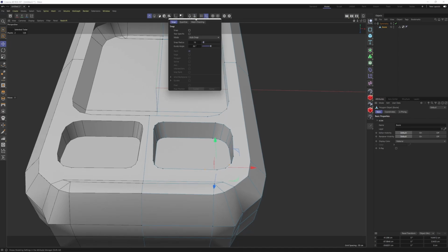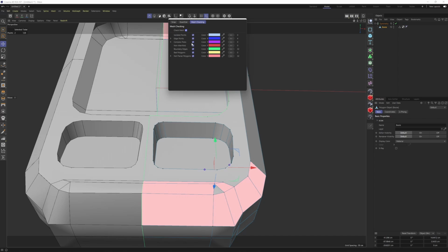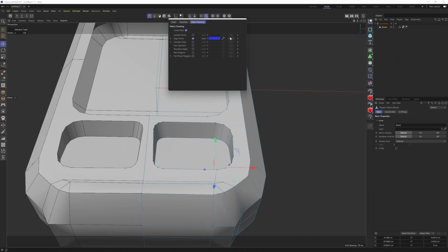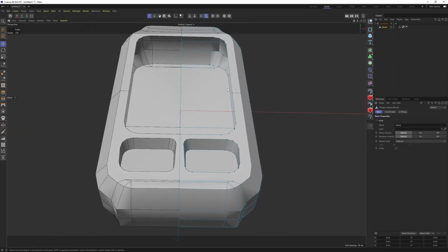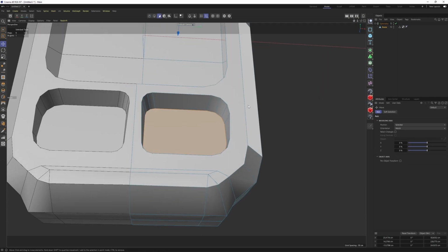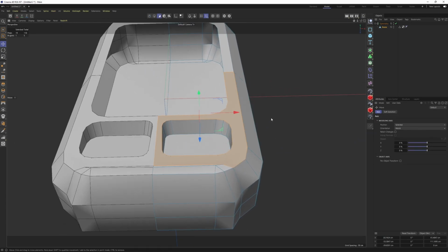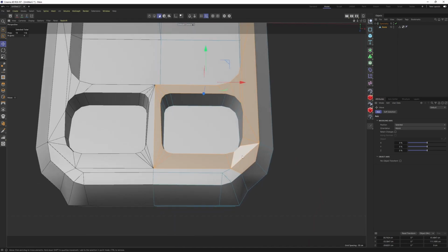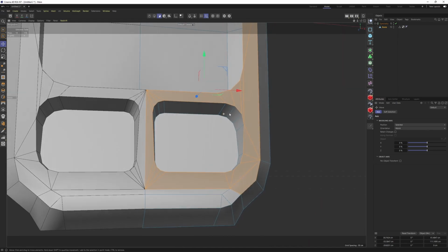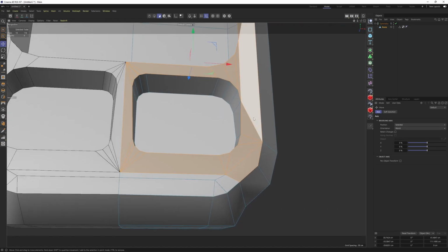And to get rid of them, there is a quick way. Go here, go to mesh checking, enable that. I will only turn on the edge points. And if you click on this one, it's gonna select all of the empty points. And I'm just gonna delete them. Now I'm gonna select that polygon islands, right click, n-gons, and say remove n-gons. Of course, this is not gonna give us a perfect result, but it's gonna be a good starting point.